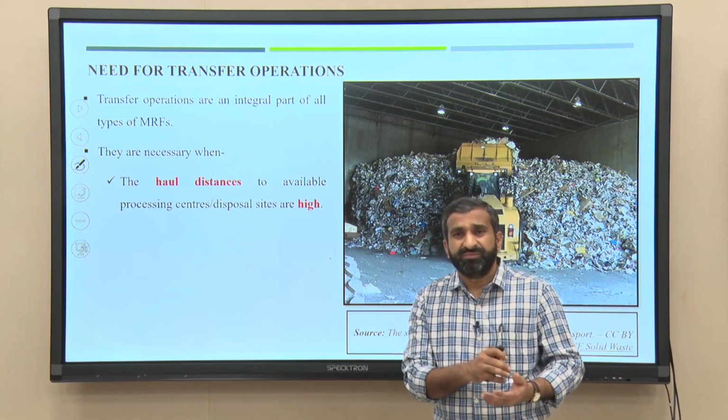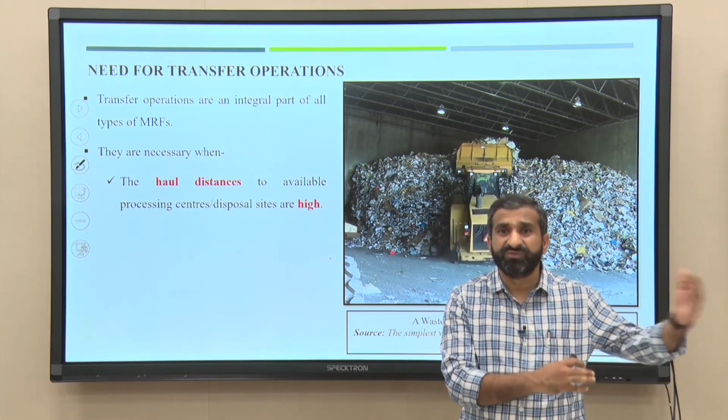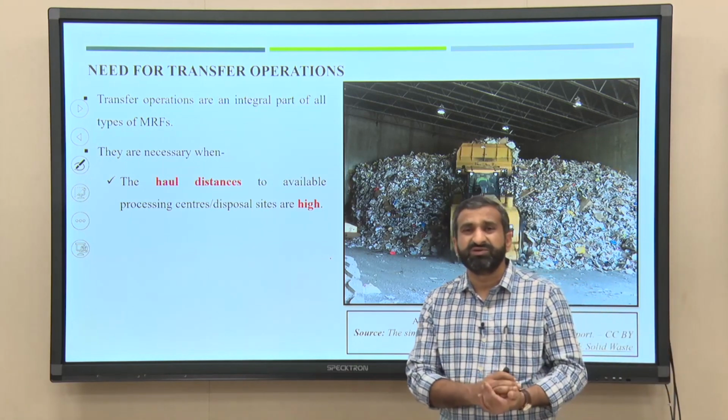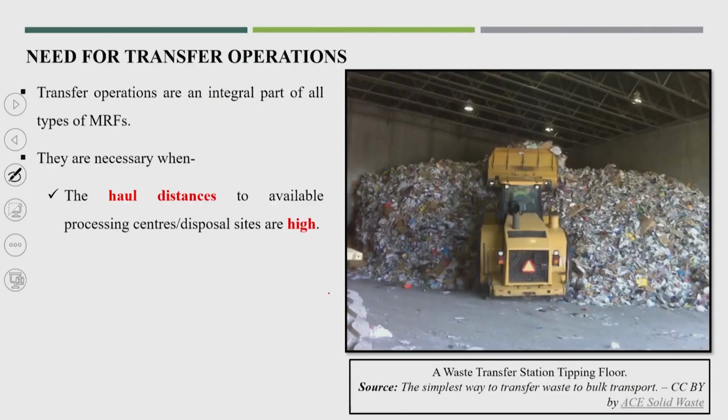But if the haul distance is more than 30 kilometers, 40 kilometers or 50 kilometers, it's very difficult to avail simple collection facilities. In that case you will require transfer stations.